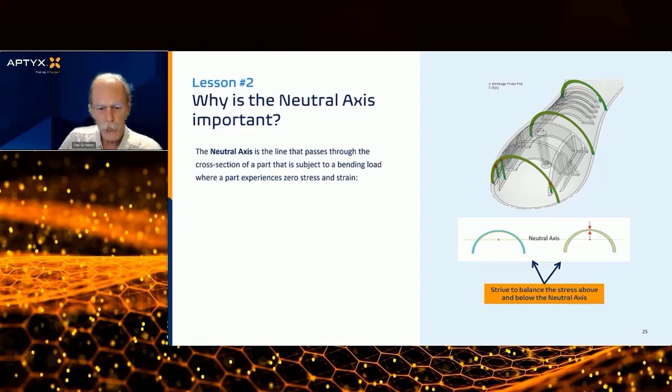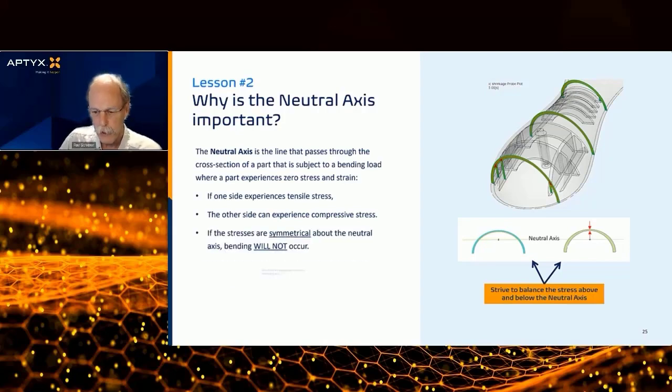We just spoke a few moments ago about the edge effects around a part. They go longer and the middle shrinks more and becomes shorter. So that forces a bend. If you have some symmetry about that point, you stay flat. If you have asymmetry around that neutral axis, your part will warp. And that's a fundamental piece that will carry into the presentation as we go forward. So just those two pieces, if you hang on to those, the volumetric shrink concept and the neutral axis, it'll all make sense to you.